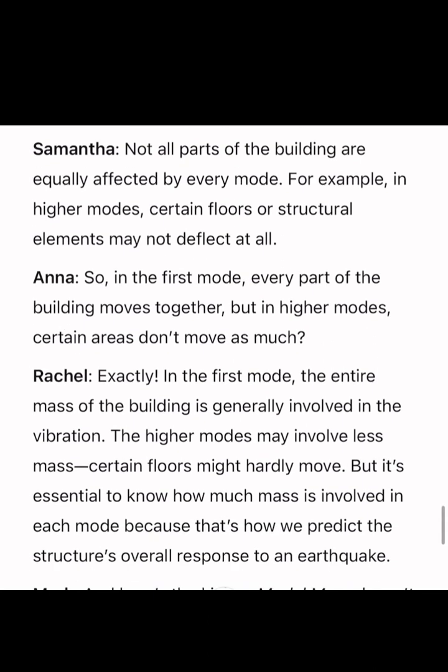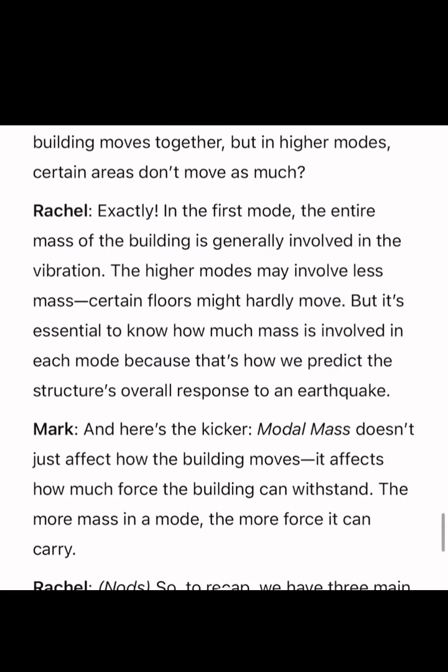So in the first mode, every part of the building moves together, but in higher modes, certain areas don't move as much. Exactly, in the first mode, the entire mass of the building is generally involved in the vibration. That's why the first mode is very important. The higher modes may involve less mass. Certain floors might hardly move,